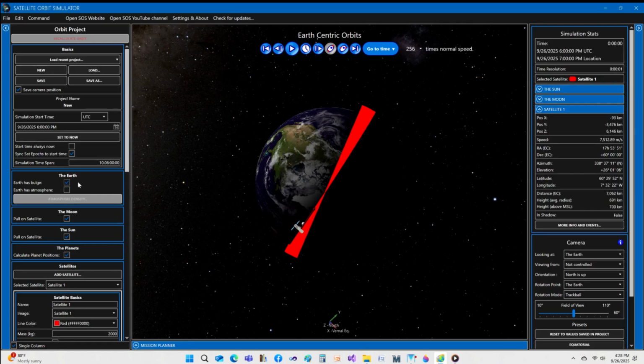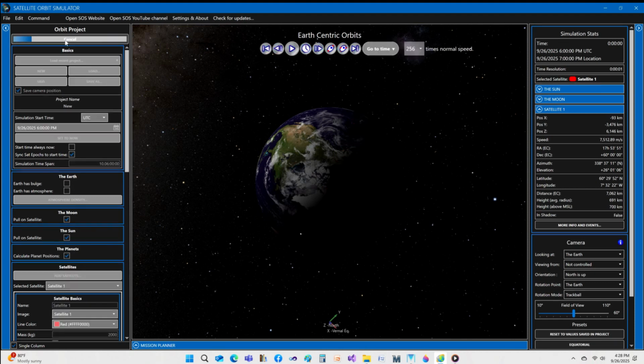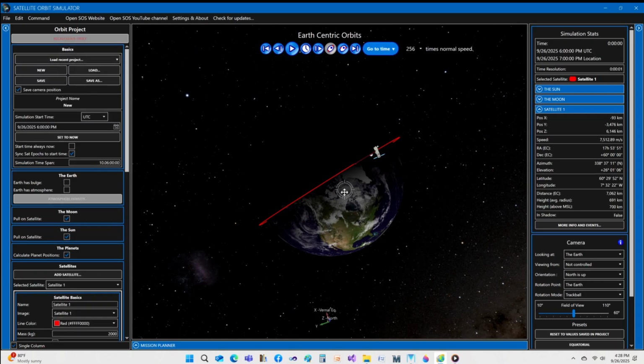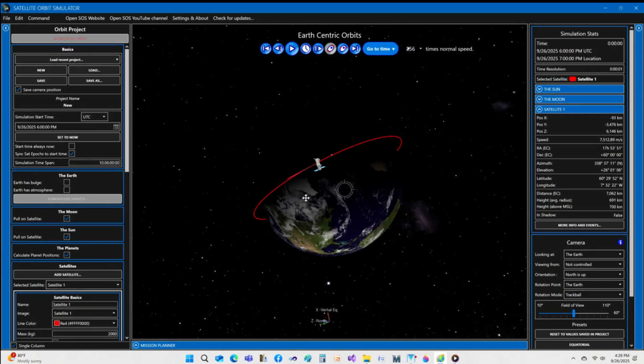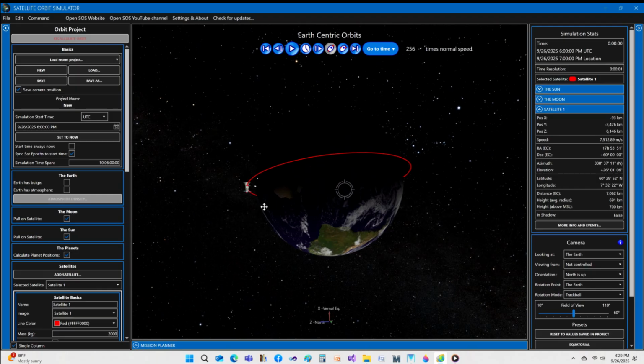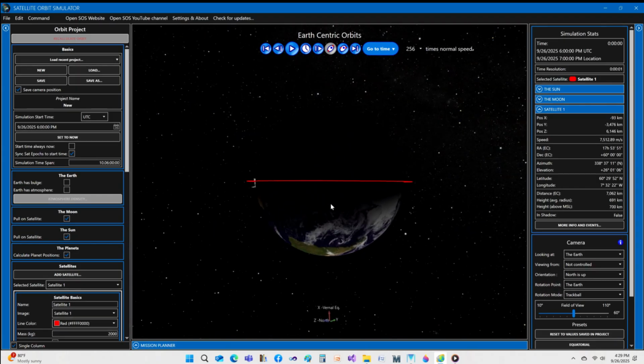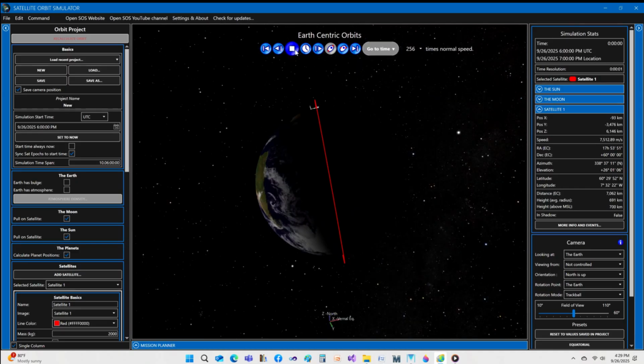For educational purposes, now uncheck the Earth has bulge checkbox in the Earth group box and then recalculate the orbit. Rotate the camera again so you can see that the satellite no longer drifts with time. One of the benefits of this orbit is that the satellite always receives solar radiation on the solar panels, eliminating the need for batteries that store electrical energy.